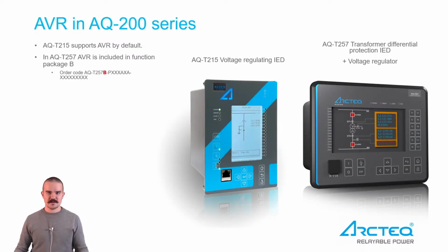This function is included in two device types in the 200 series. In the AQ-T215 voltage regulating IED, this function is included by default, but in the AQ-T257 transformer differential protection IED, you will need to define when ordering that you want to have this function included.